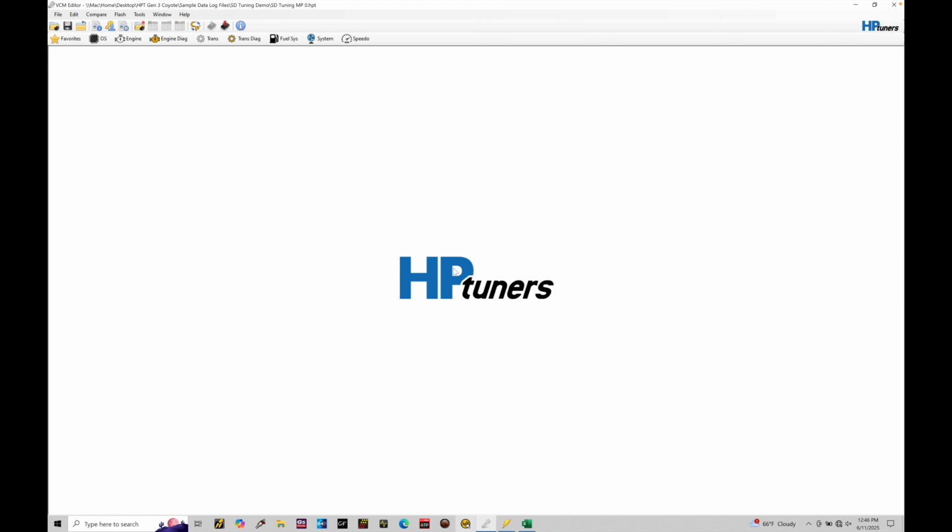Now, I am running a custom VCT schedule. We've talked about that extensively throughout other training tutorials, looking at the VCT scheduling and understanding the custom schedule. I'm calling on 6 MAP points. So I have shrunk down the number of MAP points that we're going to be working with here because I have the intake manifold runner control deleted, and essentially it's open all the time. It's making this process a lot simpler.